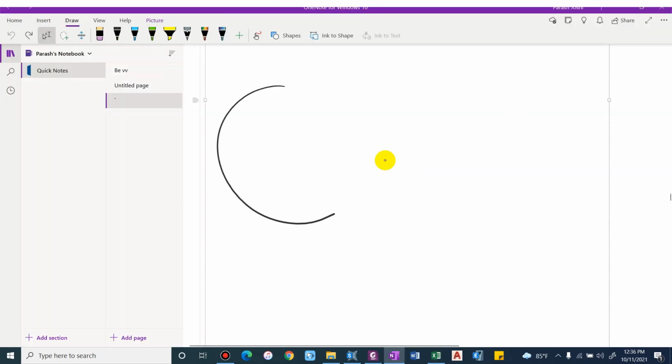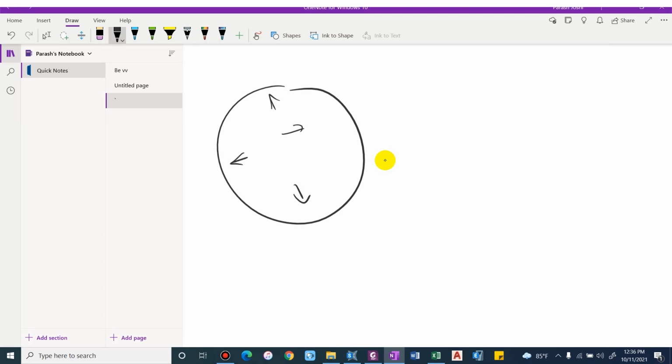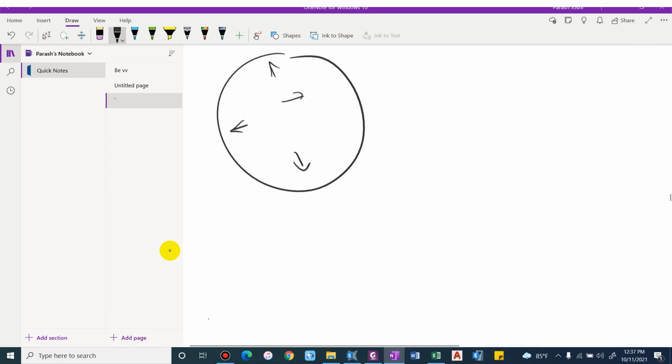So considering this as a circular tank, this is the plan view. The water will exert pressure in this direction on the wall. This is known as the hoop tension, that is, the wall tends to buckle out. So this is the hoop tension. We have to compute the thickness on the basis of this hoop tension.